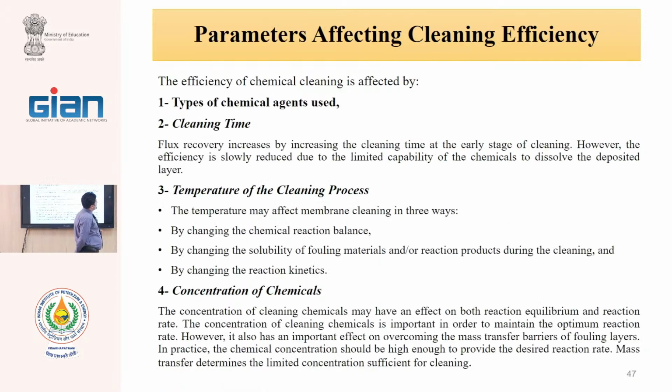The parameters that affect the cleaning: one, the chemistry of the cleaning agent that we discussed in this table, but the cleaning time is important. Sometimes 30 minutes, 1 hour, 2 hours, based on the chemicals. Temperature is important.